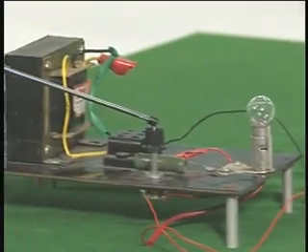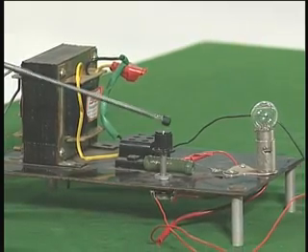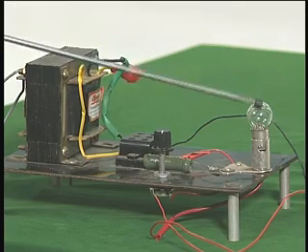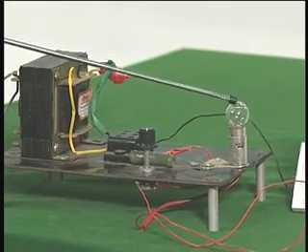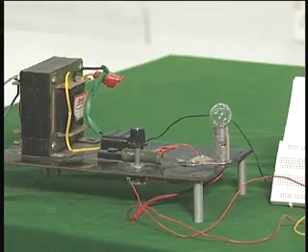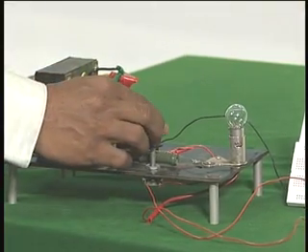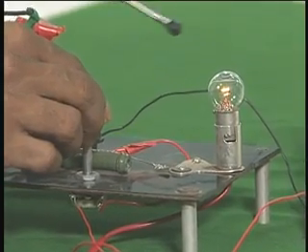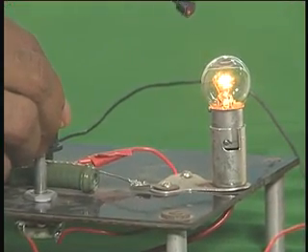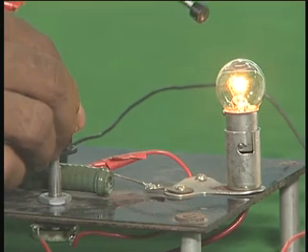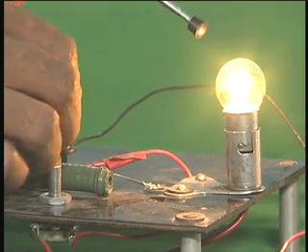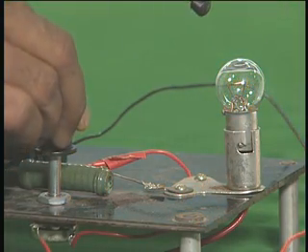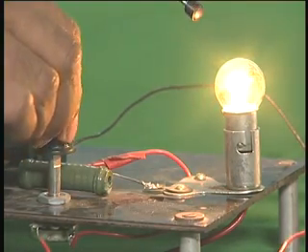So, this is the resistance which is changing the phase shift, RC phase shift, and when I change this, you would find the intensity of this light will become different. I can control the intensity. Now, I want you to look at the lamp. As I change the phase shift, you find the intensity is increasing. That means the SCR is triggered even earlier, and more voltage is applied across. Therefore, now it is very bright. So, I can change the intensity of the lamp by changing a potentiometer which is in the gate circuit. That is what I am trying to do.